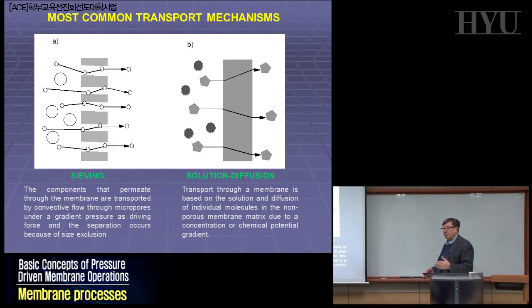So they can be materials which have cationic or anionic charge, fixed in the structure. You will see that these materials can be utilized to produce cationic membranes or anionic membranes, membranes in which what goes through is not controlled by solubility, diffusivity, or just by size phenomena, but also by what is called the Donnan phenomenon, which means electrostatic phenomena related to the necessity to respect the electroneutrality of the system.